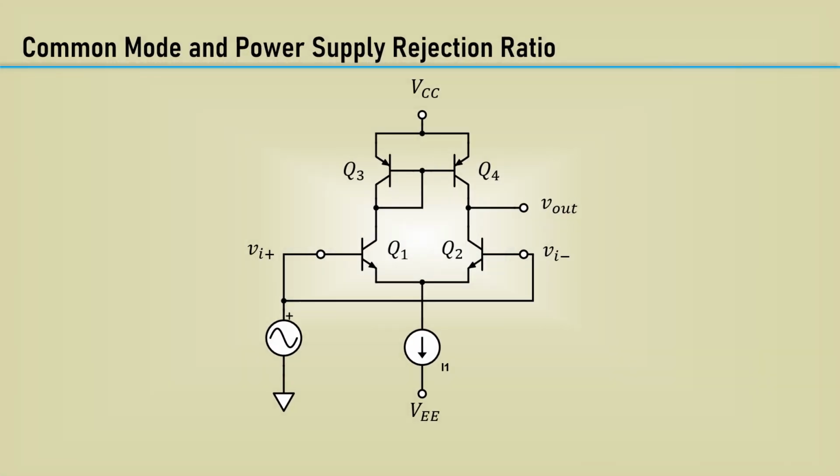In the Peek Inside the Op-Amp video, we saw how a constant current source in the emitter tail dramatically increased the op-amp's ability to reject common mode signals. But due to the inherent mismatches, there is a limit to how much can be rejected. Common mode levels change the offset voltage. We saw earlier how changes in the power supply voltage change the offset voltage too.